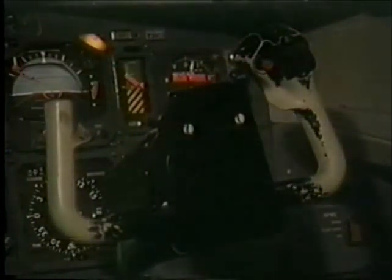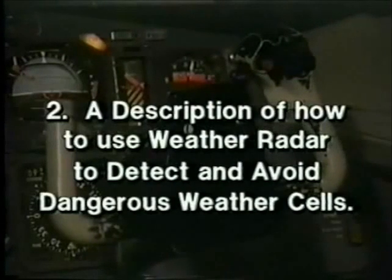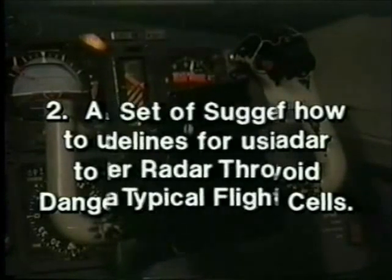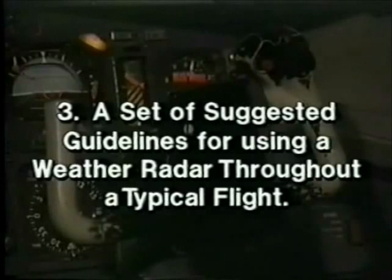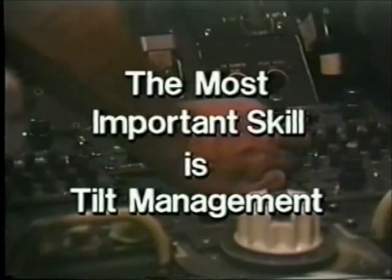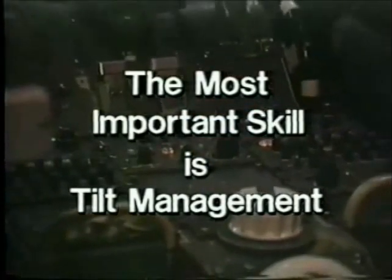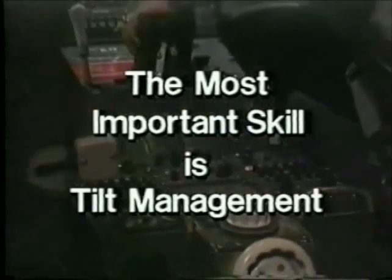This program has covered the following subjects: a basic understanding of radar operation, a description of how to use weather radar to detect and avoid dangerous weather cells, and a set of suggested guidelines for using a weather radar throughout a typical flight. It should be noted that the most important radar skill a pilot can possess is the ability to use the ground echoes as a reference point for proper tilt management.